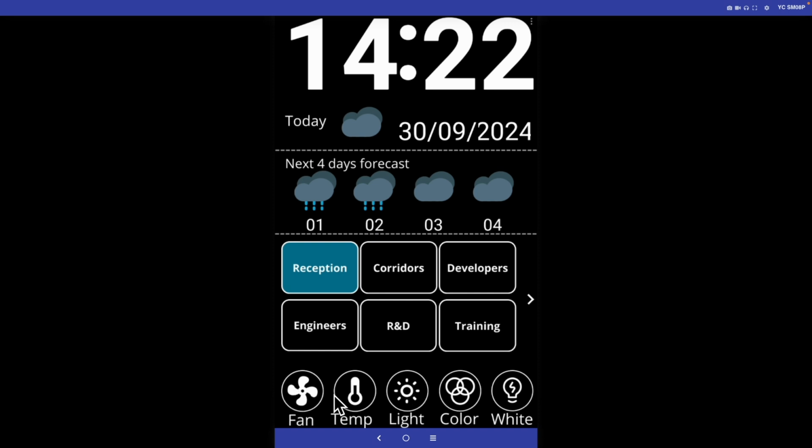It's true that we created a variable in Adquio a moment ago to store the status of these buttons, but we actually don't need it. We'll only need the zone variable, as these buttons will work in a special way, ensuring that there is always a selected zone in the upper area, as it's impossible for none to be active. When we press any of the buttons, the previously selected one deactivates, but it never allows all the buttons to be deselected. Since we always have a selected zone, we can now make these buttons link to a specific control window for ventilation. Depending on the selected zone, we can control ventilation, the temperature of that zone, and so on.